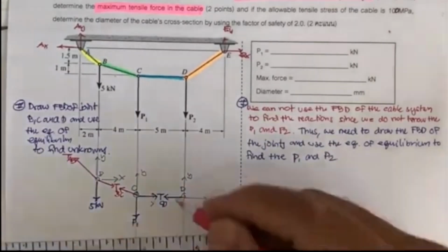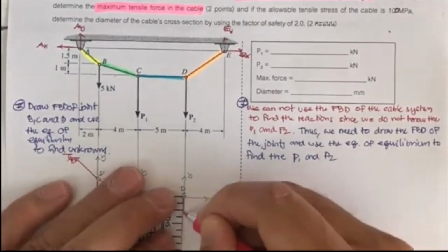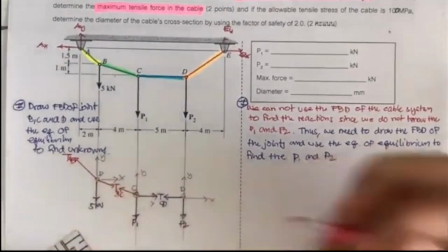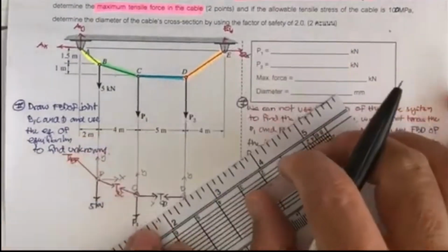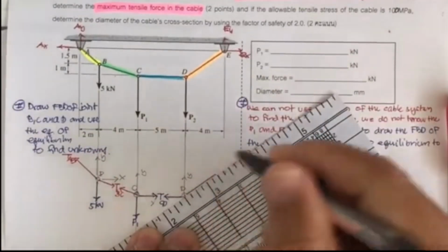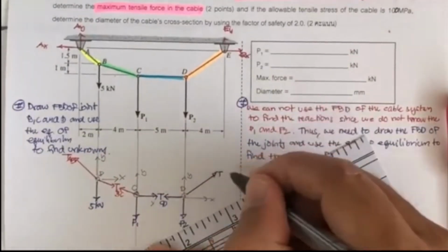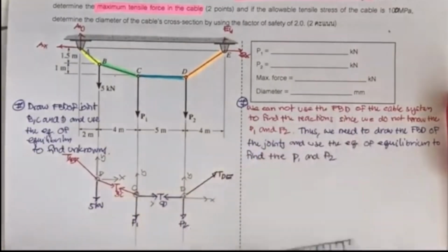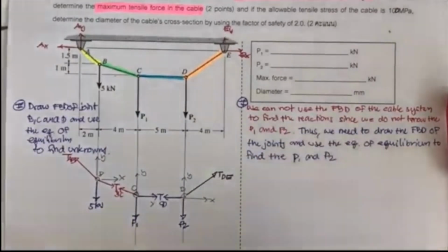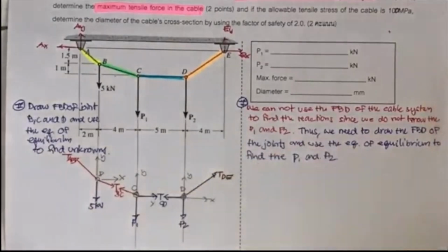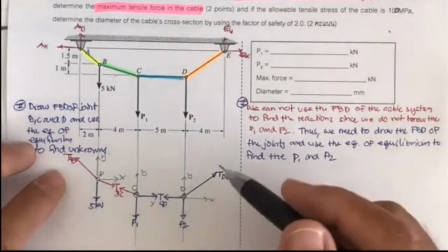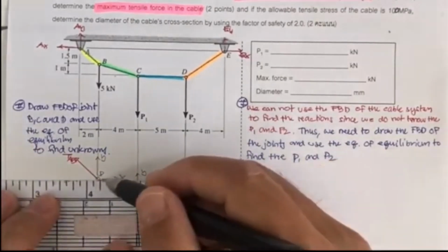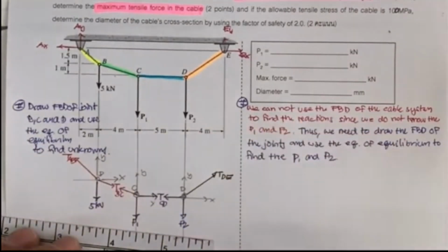And then due to the P2, you're going to have the tension in this cable. Let's call it T sub DE. Okay, we have all of the free body diagram, and then you got to determine the angle that the cable acts with the horizontal axis.